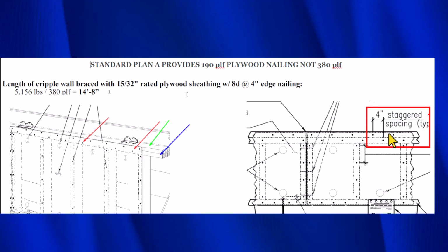Now let me show you why that's a problem. So if we come over here, say this is an L90 framing anchor. The L90 has nails that go in 1.5 inches. So they go 1.5 inches into the upper top plate. They do not go into the lower top plate. They go into the upper top plate. So when the earthquake force comes, the joist is sliding, and when it slides, it's going to go into the nails in the upper top plate only, because that's what it's connected to with the 1.5 inch nails.